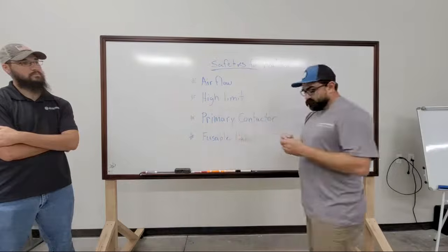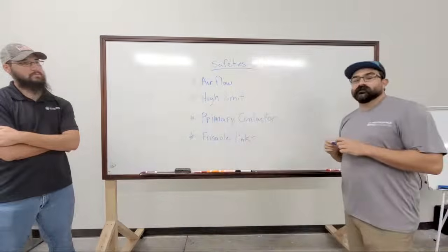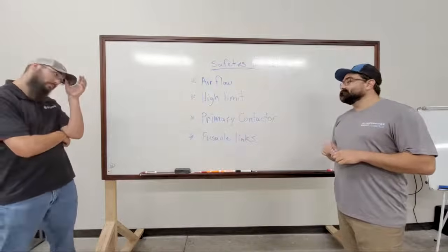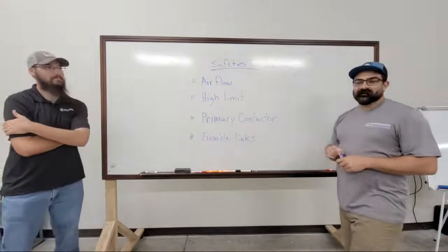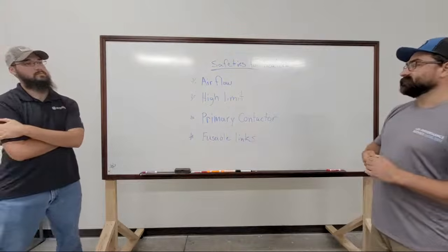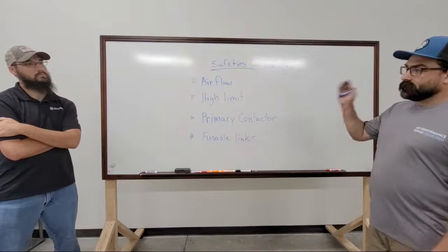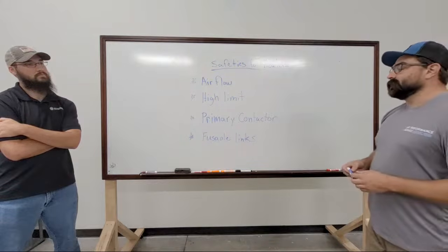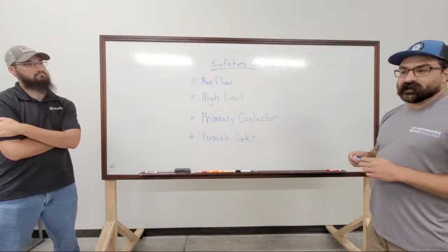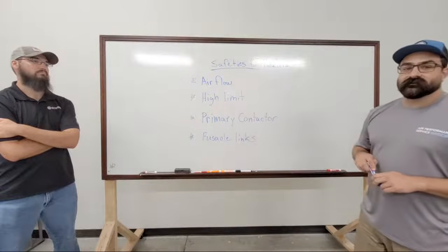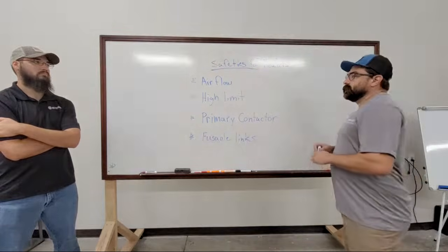One thing to note before we go into this is hot water usually does not have any kind of safety, at least as far as control. We're specifically mostly talking about electric reheat here. Hot water valves are usually just out there on their own. There's no safety inside of the control system.